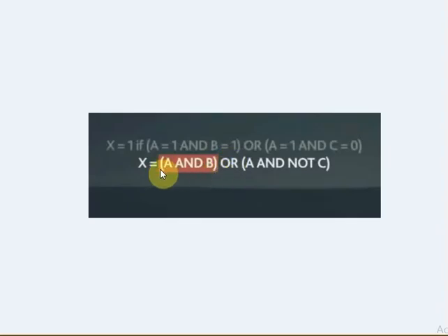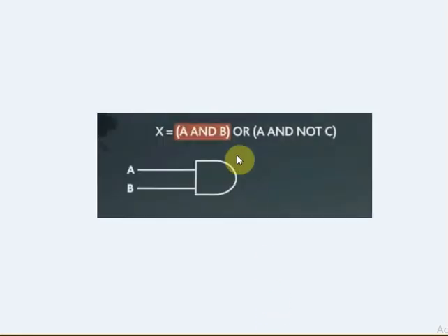So one branch is this, because they are clearly bracketed here, no? The one branch is the other side. So then we need to start from the OR gate and write one branch and the other branch. Very simple, no? A and B, A and not C. Now here this is the AND gate. A and B. Right, correct. A and B is written.